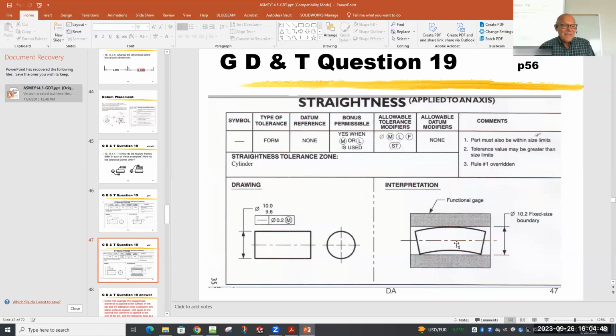I'm kidding. Well, I'm not kidding, because really you applied geometric dimensioning and tolerancing, because what you said was that hole is apparently too small, which means it's probably at max material condition. But it doesn't have to be. I can make it least material condition. It'll still work by making the hole bigger. When you make the hole bigger, you're taking advantage of the fact that when the hole is as small as it'll go is the time when it's least likely to work.